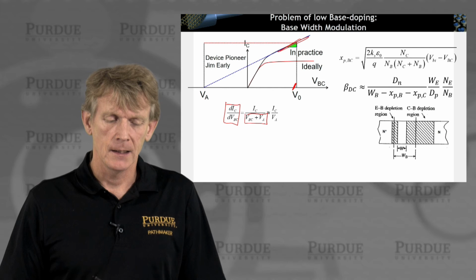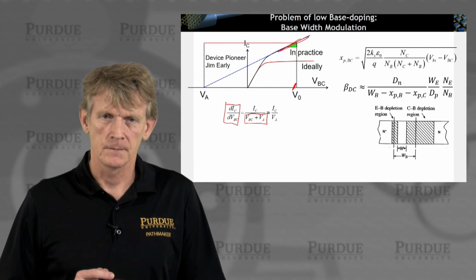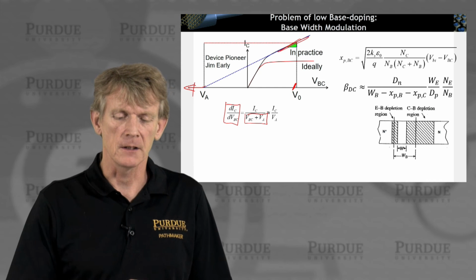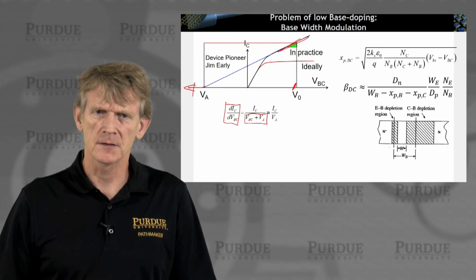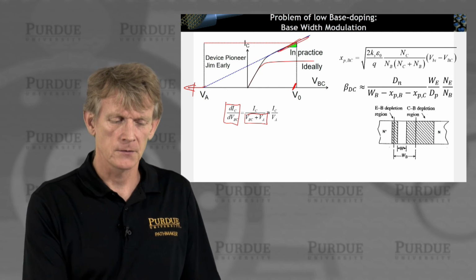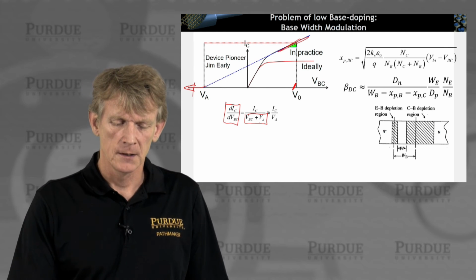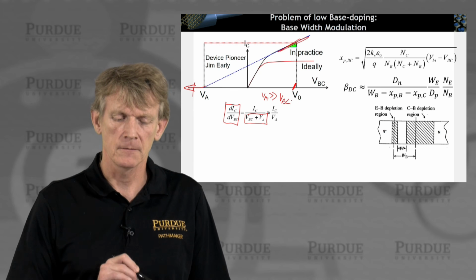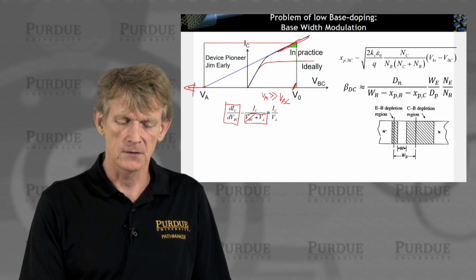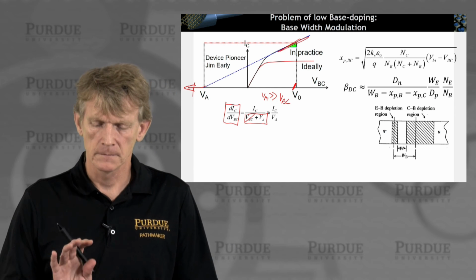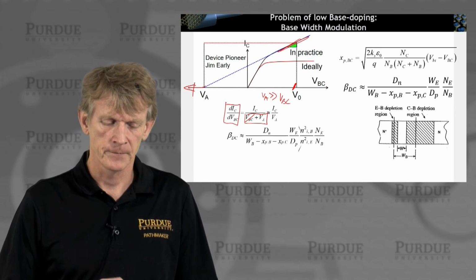Now, in an ideal world, you would want to have this move to infinity, right? And for the argument's sake here, this slope is pretty much exaggerated, okay? So you can assume that VA better be much bigger than VBC, okay? So we're going to drop this dependence here. So we'll just call it IC over VA. Okay, just to make life a little simpler.